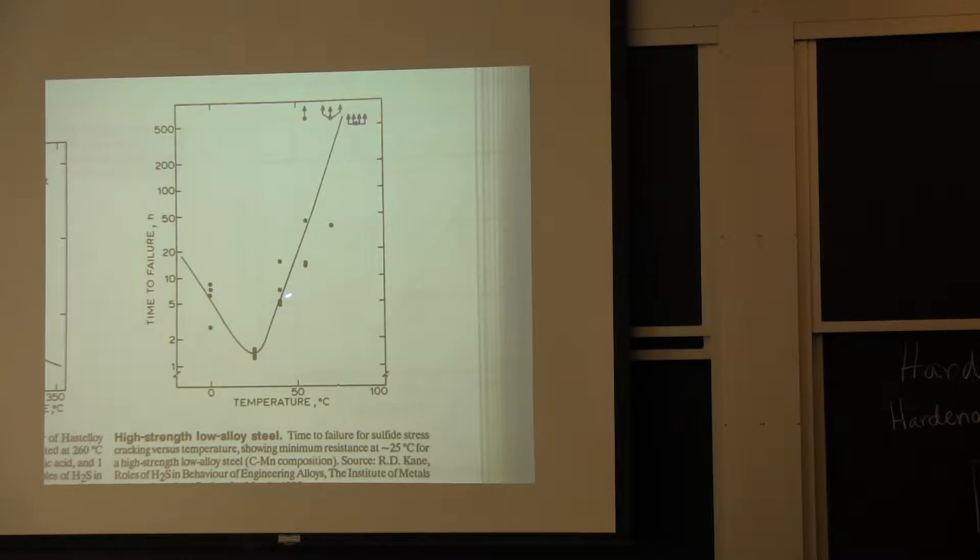Anyway, this is time to failure versus temperature. At 25 degrees C, which is room temperature, we have cracking in less than 2 hours. If we cool down, it takes up to 20 hours because the hydrogen can't diffuse to the crack tip. Yep.